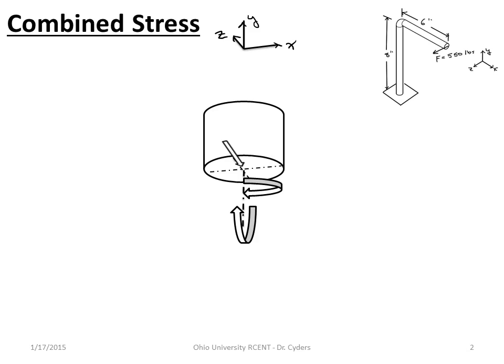And so we can zero in on this as probably the cross section I need to focus on, because these two stresses, the transverse load and this torsional load, are the same anywhere along here. And so this bending moment is the one that's going to change the state of stress and increase that state of stress at this point. So we've got these three loads. Let's calculate them and look at how they combine.